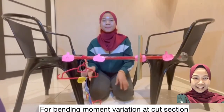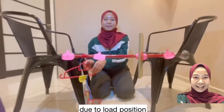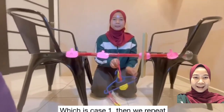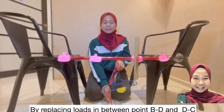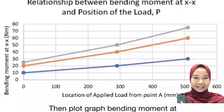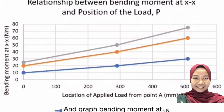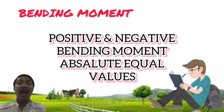For bending moment variation at the cut section due to load position, after we complete the trial in section AB, which is case 1, we repeat the same procedure as case 1 by replacing the loads in between points BD and DC. Then, plot the graph of bending moment at section XX versus position of load and the graph of bending moment at section XX versus magnitude of the load.